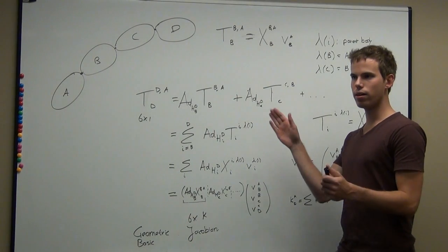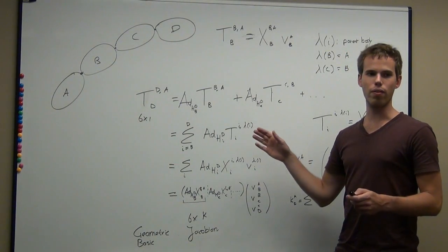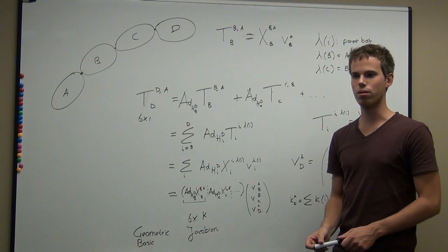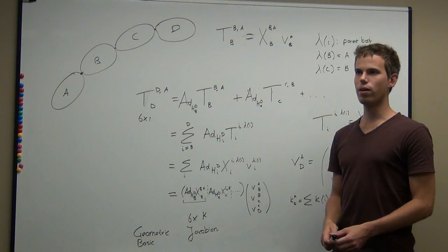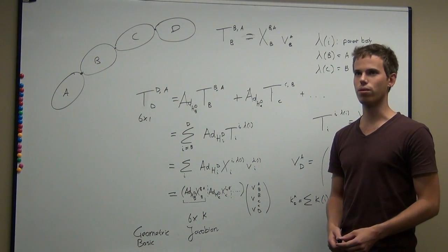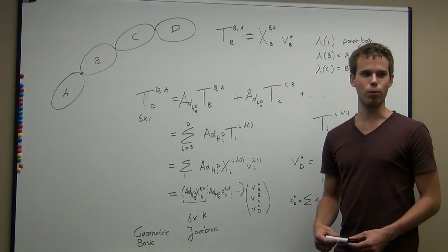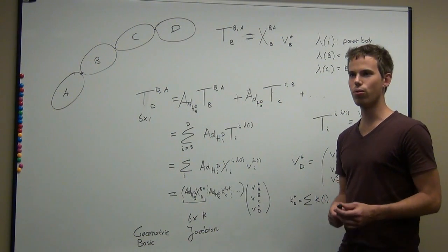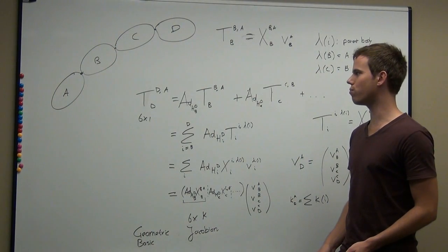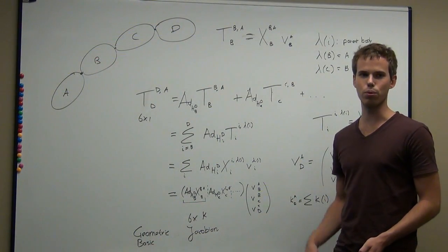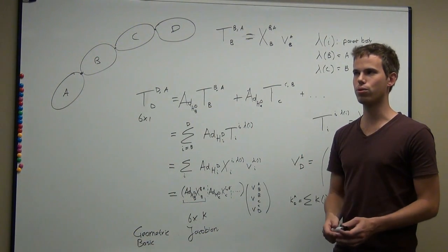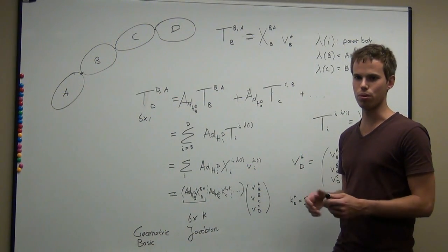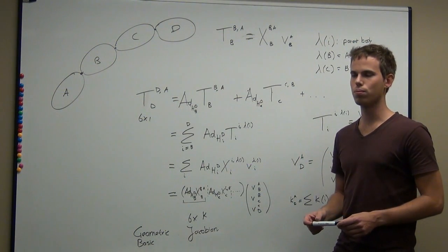Then they concatenate them all together, and use the derivative function in Mathematica or in Maple, and let it go for like a day and wait for an answer in terms of all of the joint angles. But really, you don't need to do that, because you already have all of the information that you need from the motion subspaces and the kinematic tree. So this is a much easier way to calculate those types of Jacobians.